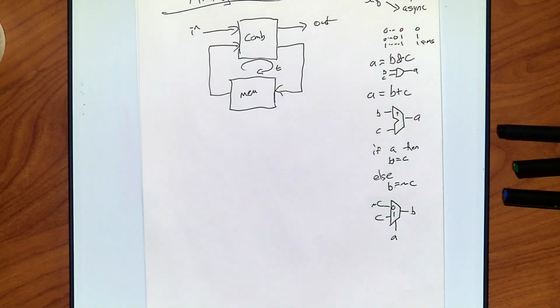But an if statement is understandable as a mux. So you can start to see, I can actually take your program code, even control commands like this, and start saying what is the equivalent piece of hardware and how do I cascade them together.